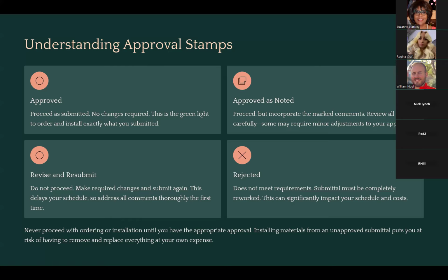So they're just going to say, yep, reviewed with no exceptions. So if you get a submittal back and it says reviewed with no exceptions or no exceptions taken, it essentially means approved. It's just a legal way of the architect or engineer responding without saying they really approved it. That always annoys me when they do that, but sometimes they will do that instead of saying it's approved. They'll just say it's been reviewed.